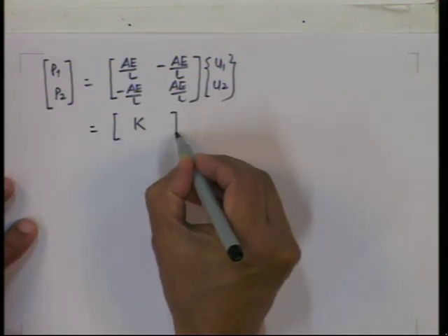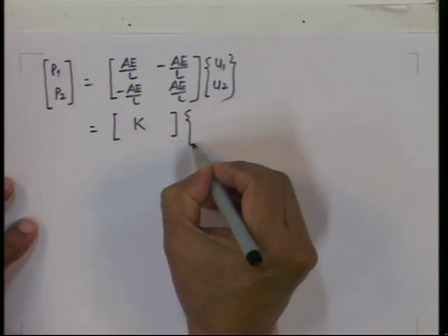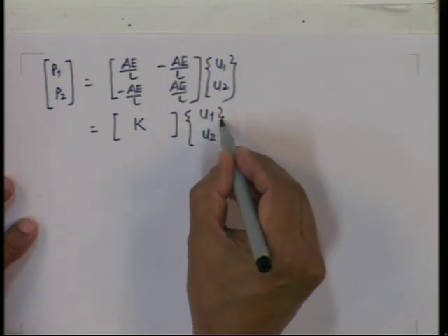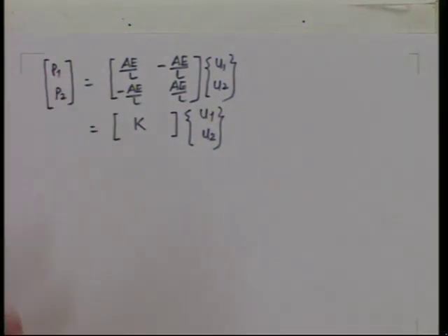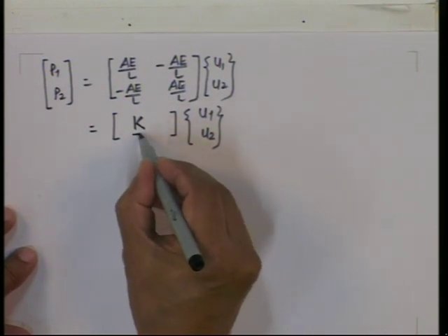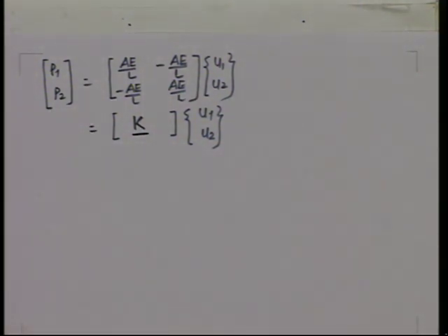of the member or element, whatever you want to call it, because this relates all the generalized displacement to the generalized forces acting on the nodes, and whatever is in between is called stiffness property, and this has a physical meaning. This is stiffness. That is why we are used to stiffness, that this is a stiffness matrix, while in a thermal problem this was not a stiffness.